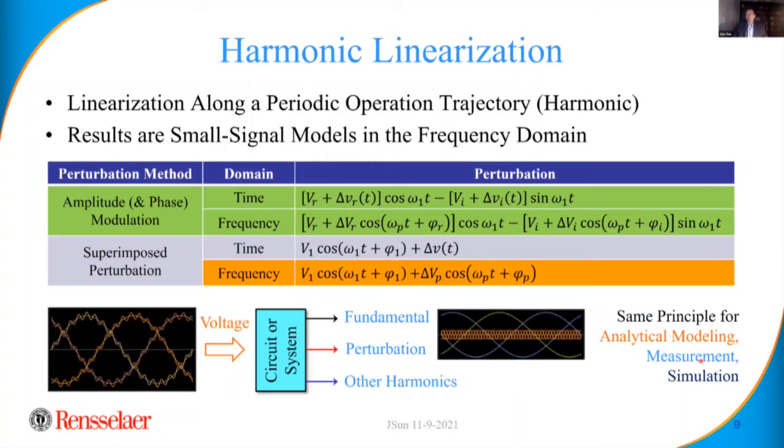We can also run simulations. So we have a detailed simulation model. We can introduce a perturbation like that, run the simulation into periodic steady state, and then do similar analysis numerically to extract the frequency response. And you build the frequency response point by point. That's what we call frequency scan. You can scan the response over frequency. And we can do that by measurement or numerical simulation.